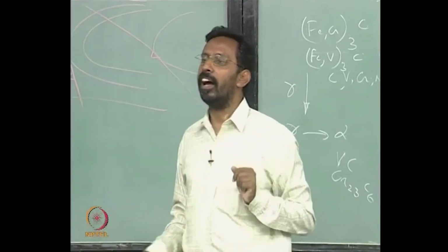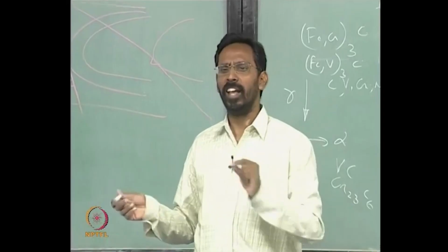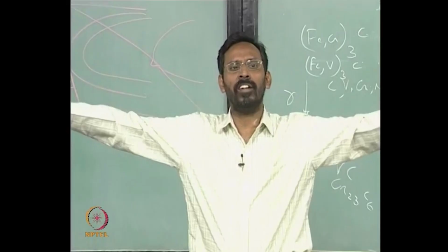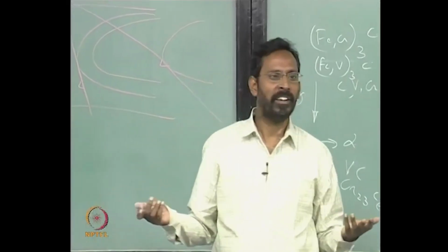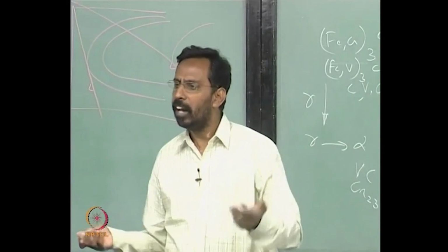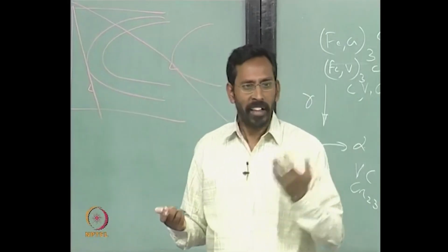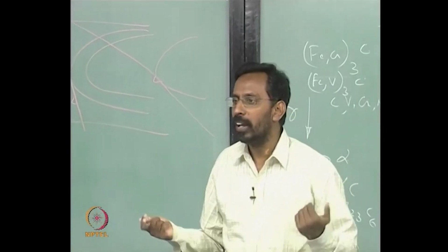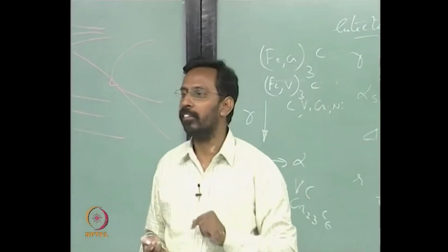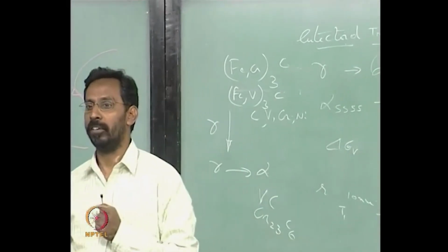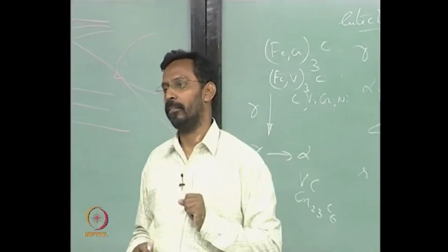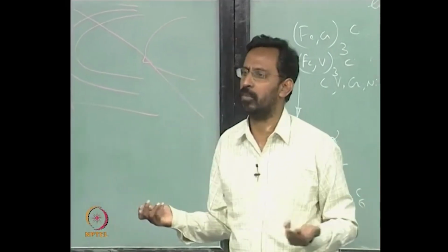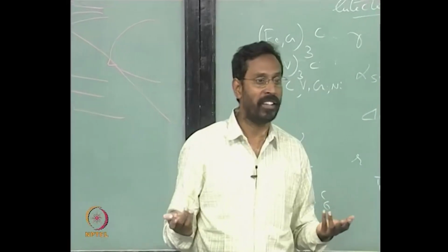As long as there is, let us say, carbon available. Let us say iron and tungsten. Tungsten cannot dissolve into iron, so iron and tungsten will come out separately. It is like iron and lead. Lead does not want to dissolve into iron, so lead precipitates out. Such a precipitation, as far as pearlite formation is concerned, is going to aid the pearlite formation, because you have a second phase sitting there. If the element cannot dissolve, it will precipitate out. There are so many immiscible systems. Iron copper is one such immiscible system.